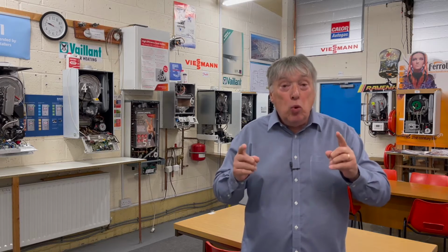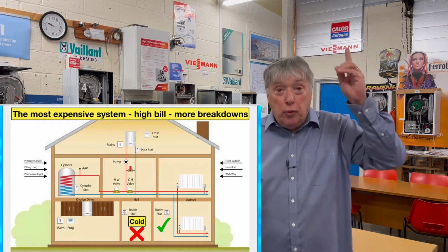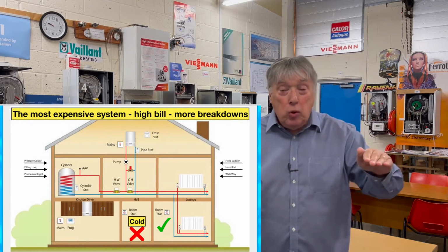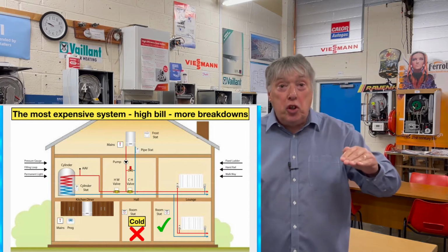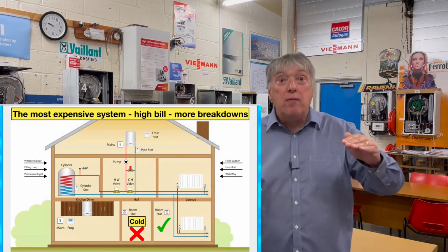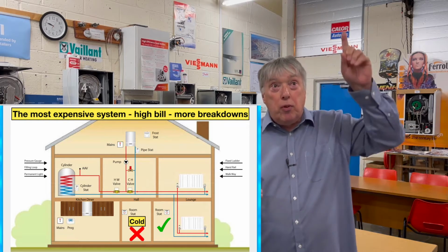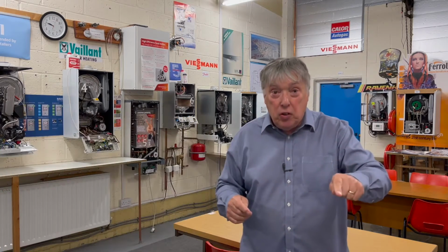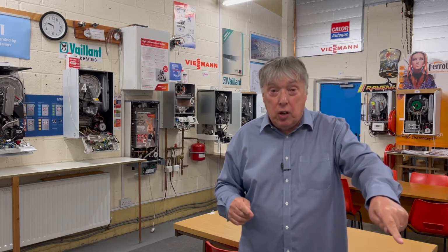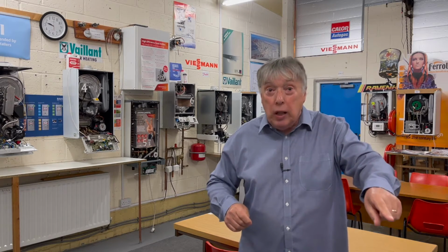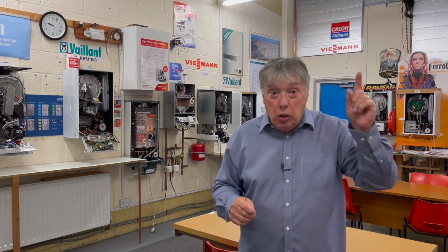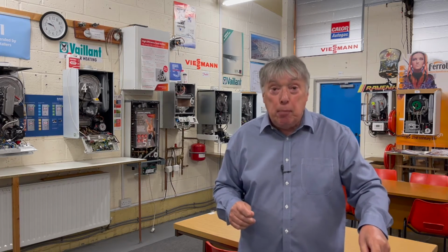The problem you need to remember is that if your boiler is up in the loft, you can't do that. You've got to add at least 3 or 4 or even 5 kilowatts on top of your radiators, because going from the loft down to that furthest large radiator in the hall or lounge is going to lose an awful lot of temperature.